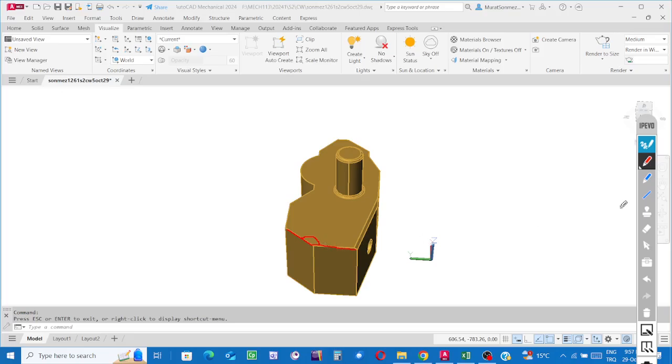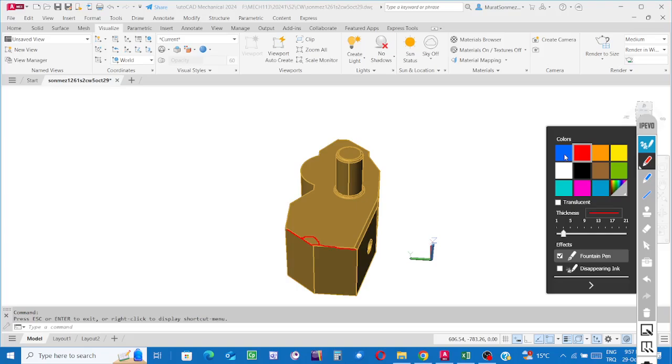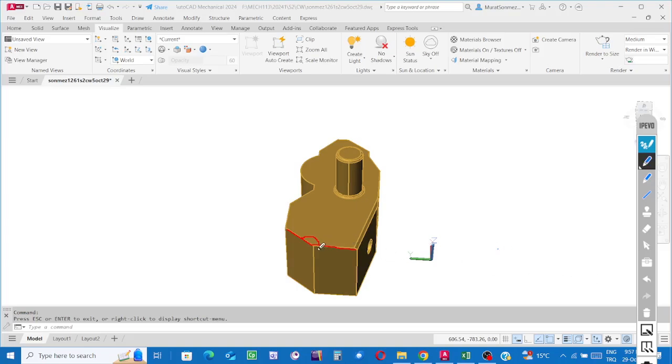Since it is so, when we coincide, for instance, the x-axis with this intersection, then the y-axis, which is orthogonal, will extend like this and will not coincide with this edge. Since it is not coinciding with this edge, we have to determine the location dimension for the second point. This is the second point, for instance.